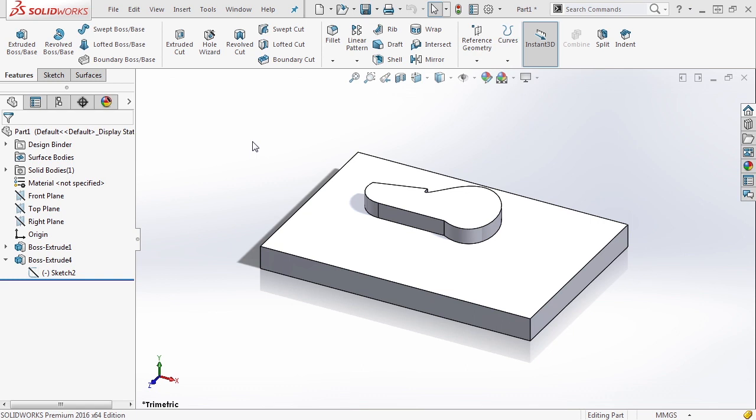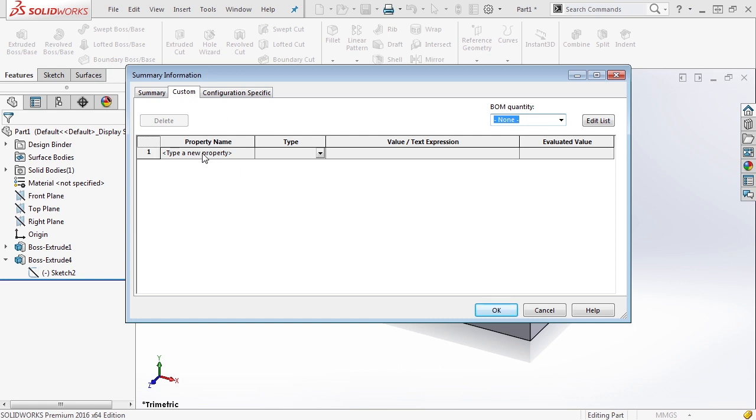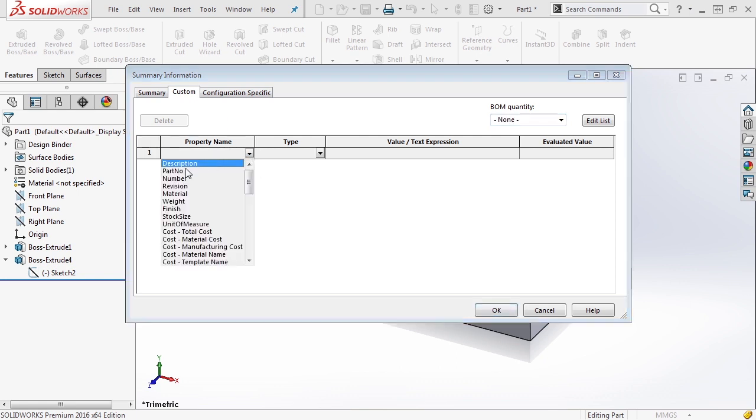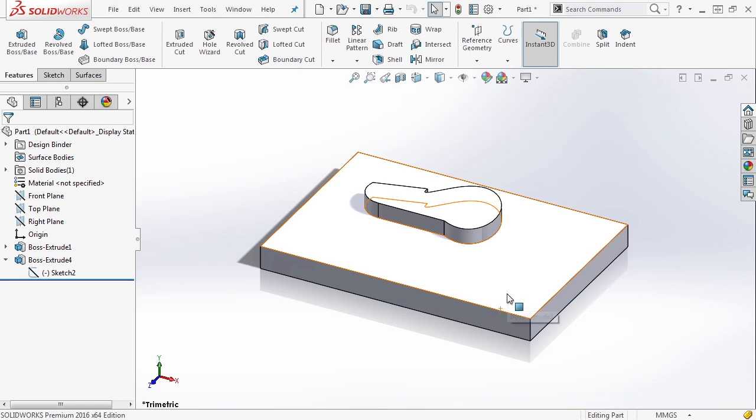To finish off our area talk about customization, let's talk a little bit more about file properties. Now, we have two different types of file properties. We have our custom properties, which is where we entered our part number, and these are great areas for you to do things like add material, add information about the weight of the finish, because these properties can be linked to various things when you start creating drawings or assemblies, or even adding them later on into other areas such as design tables and so on. So this is a great way that can add information that's attached to the file that you're dealing with.